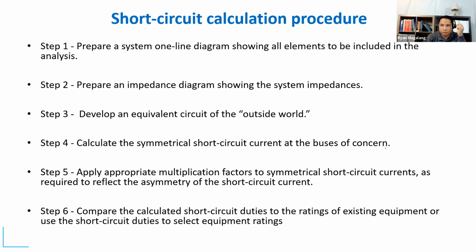They take this information from the manufacturers. So for cable manufacturers, they would take that information and put it in their database. So you don't have to check and look up this information by yourself. So, pick from that database, and the information is there. The value of the resistance, the reactance, etc. is there. For motors, they also have the information there, etc. For all of those different devices, transformers, utility. Of course, you have to get that information from your utility.